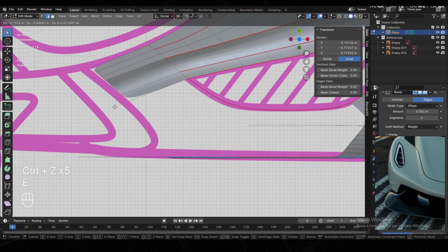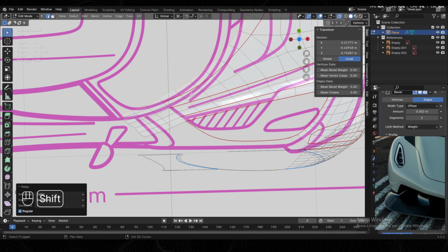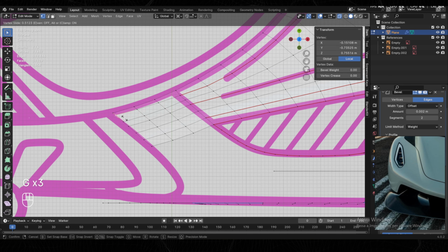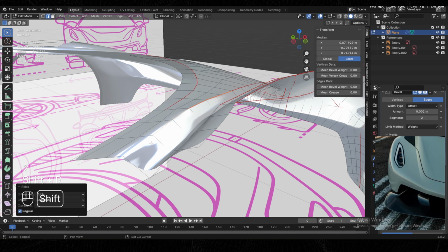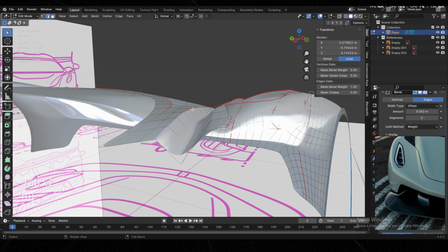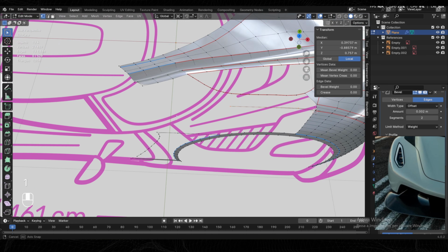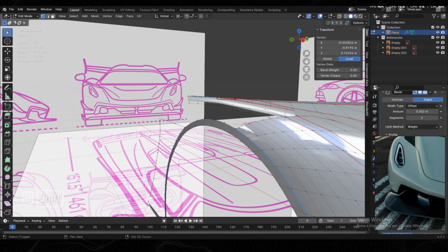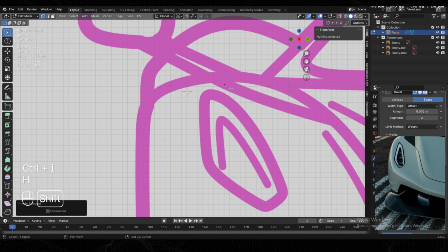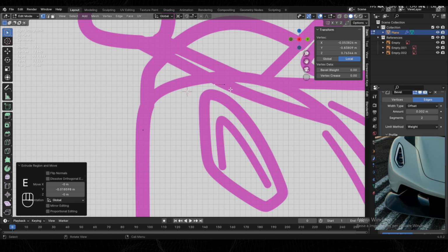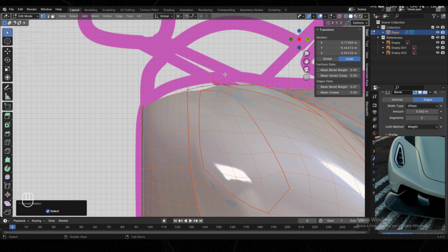Once you finish that, go here on the back of the hood and extrude these vertices. Then add 2 loop cuts in between. Adjust them on the blueprint and apply the bevels on all the sharp corners. Now that you have this new geometry, isolate these vertices and create this curve into side view, following your blueprint.